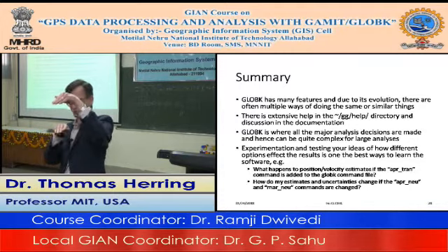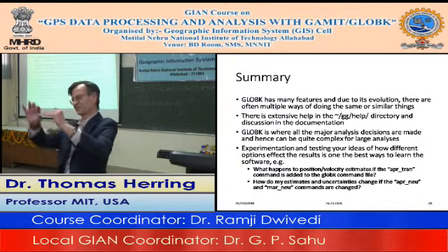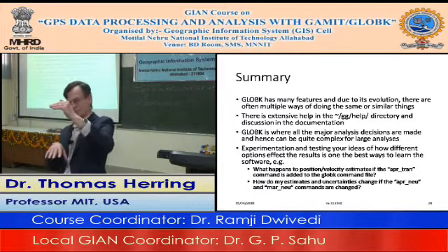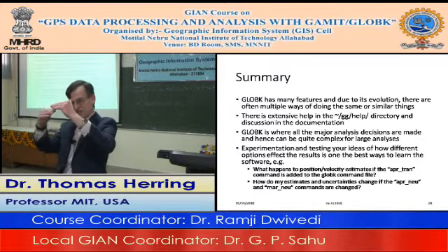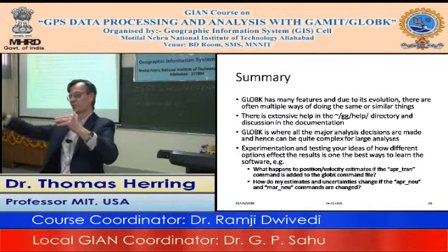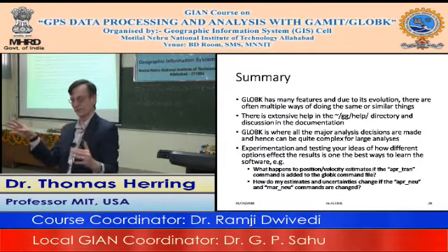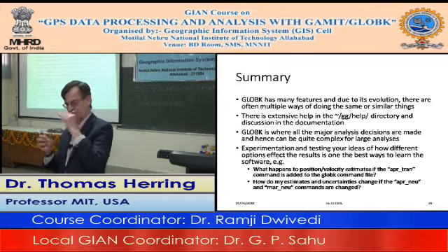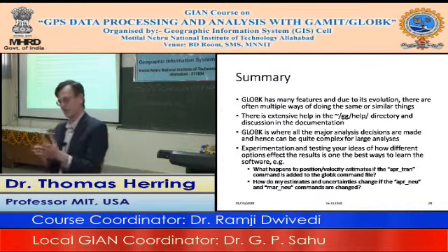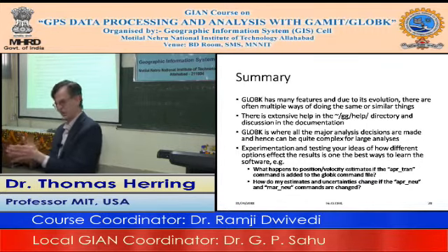When we run GLRED, it will take each of those H files and do to it what the GLOBK command file says to do. If we run GLOBK, it'll take the 30 H files all together and run the sequential Kalman filter, doing what the GLOBK command file said to do. So they're both running GLOBK. It's just that in GLOBK, all of the files are combined together as a sequential Kalman filter. In GLRED, each one is done separately as you go through. That's the distinction.